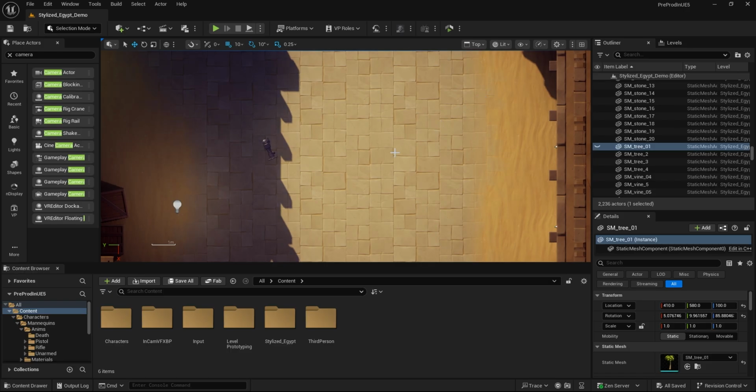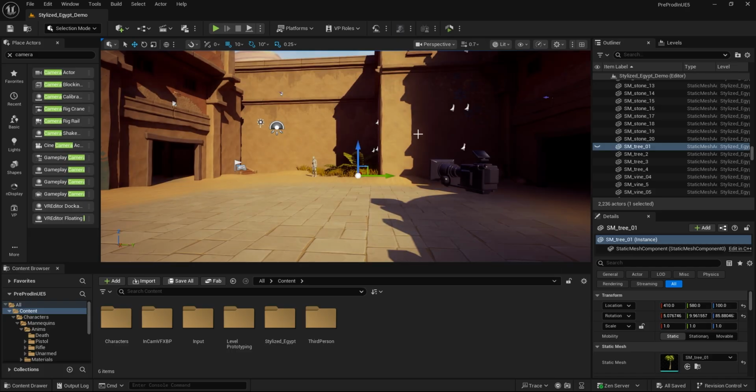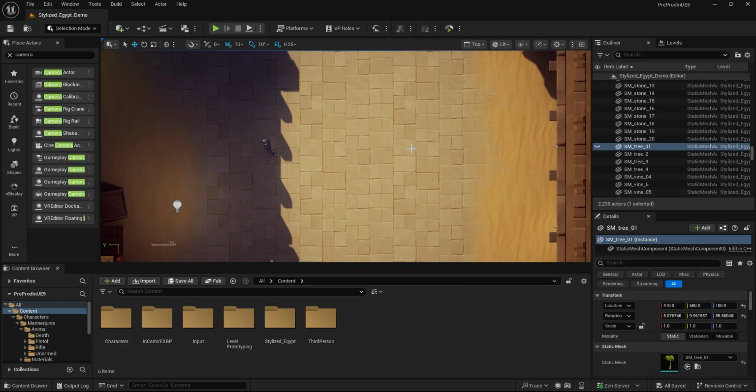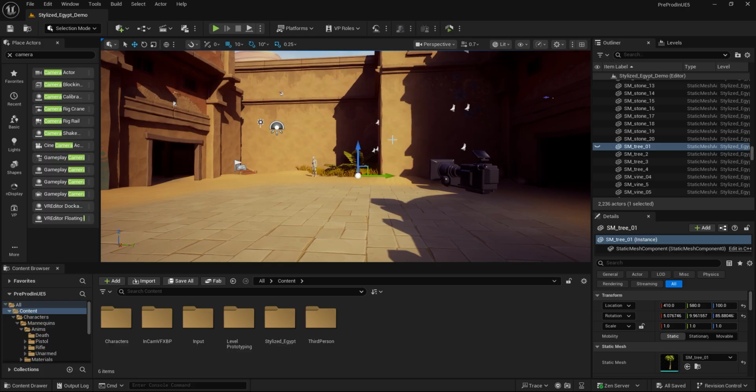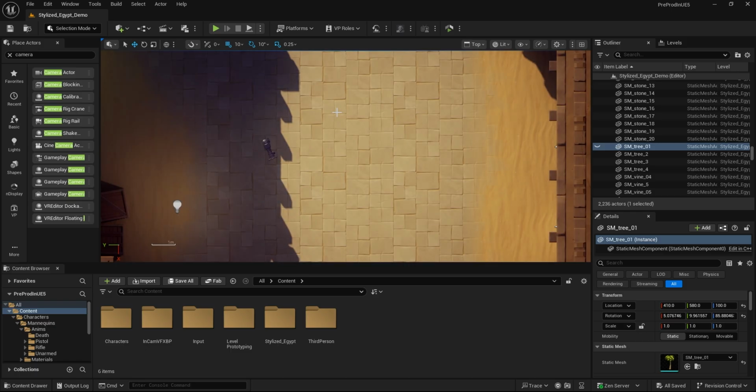There are other ways of changing to top camera mode. The first is the keyboard shortcut Alt and J. Alternatively, you can hold the control button and click and drag using the middle mouse button in the viewport. This will create a line in the direction you dragged in. To get to top view, you need the line to move straight upwards, or north if you imagine it as a compass, and then let go of the buttons. To change back to the perspective camera mode, you'll want the line to be moving southeast, again if you were imagining it as a compass.